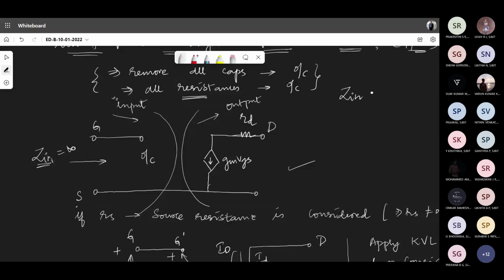Remember, when we quoted the differences between BJT and JFET, we said input impedance is very high, output impedance is very low. And what is output impedance? It is just RD value, which is a very small value. We normally make it 0. By writing this equivalent model itself, we wrote it. We did not have RD, but I'm bringing this RD here to make you understand that the resistance offered at the output is a very small value. So this is the advantage we gain out of it.